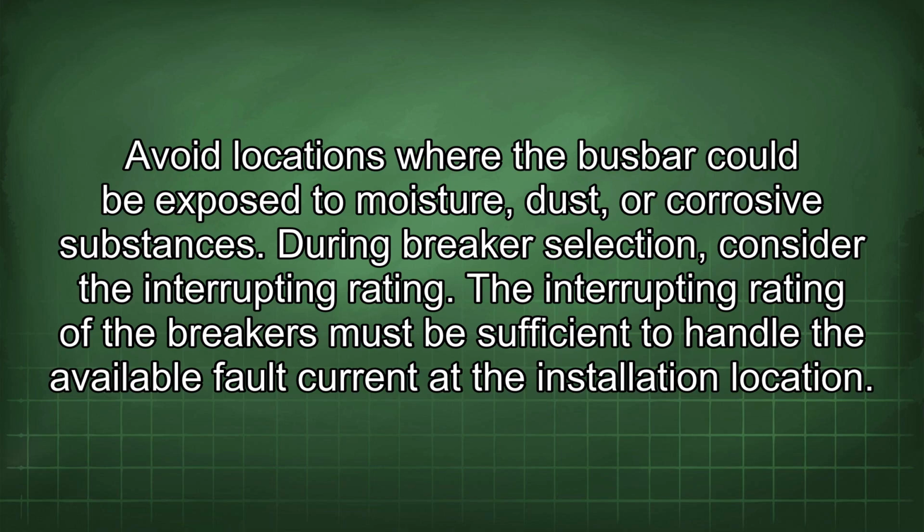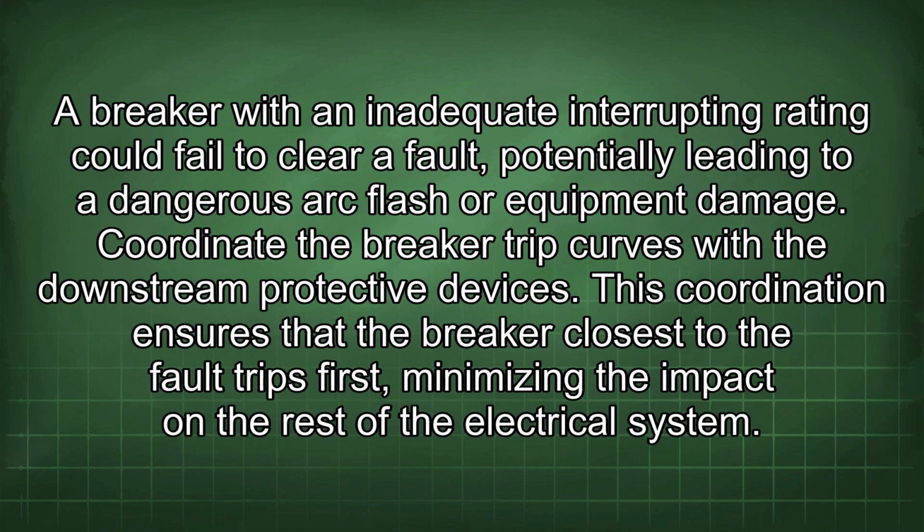During breaker selection, consider the interrupting rating. The interrupting rating of the breakers must be sufficient to handle the available fault current at the installation location. A breaker with an inadequate interrupting rating could fail to clear a fault, potentially leading to a dangerous arc flash or equipment damage.